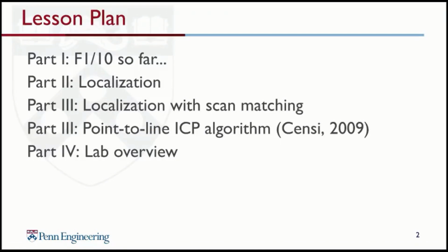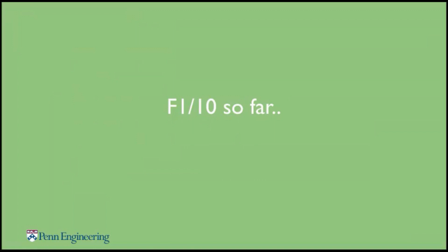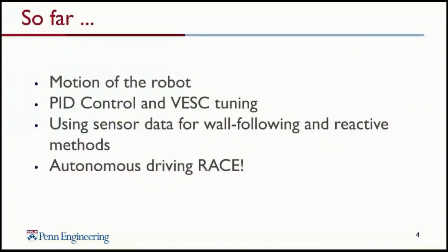In today's lecture, I will introduce the concept of localization and the motivation behind it, as well as the specific approach to localization using scan matching called the point-to-line ICP algorithm, presented by Censi et al. in 2009.